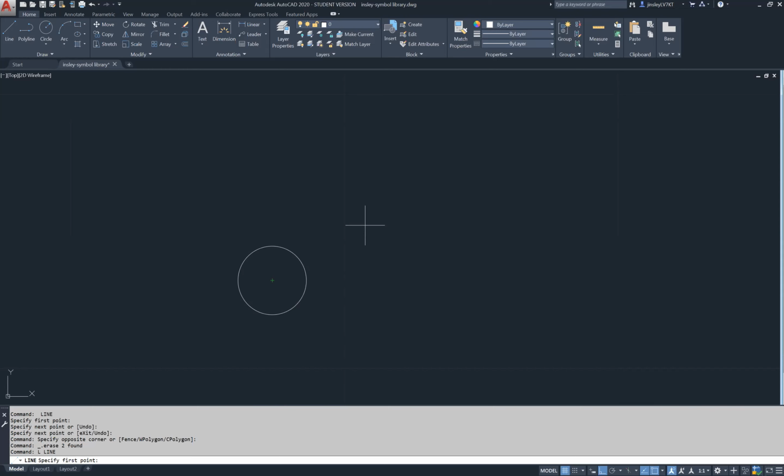When AutoCAD places those markers, it will track away from them. That tracking ability is this button that we see down below here. We have our object snaps, and beside it we have our object snap tracking. Any object snap that we currently have active, I can turn on a few more if I want to, AutoCAD will track them.